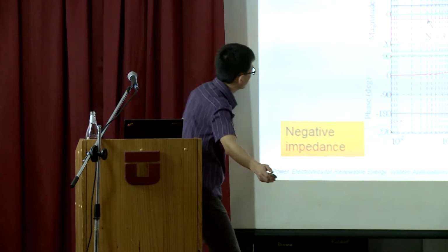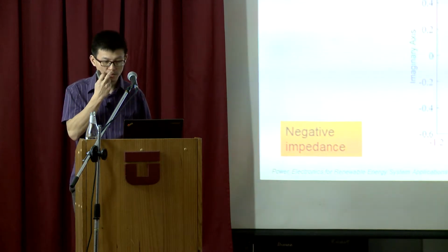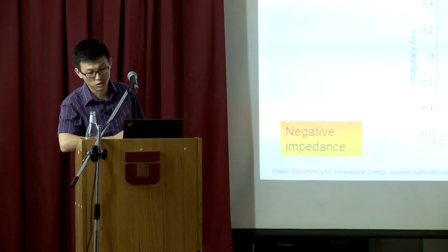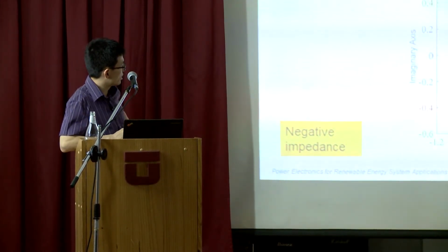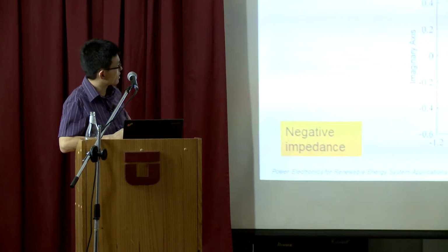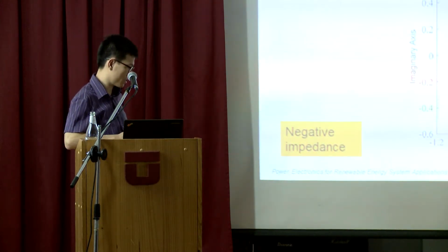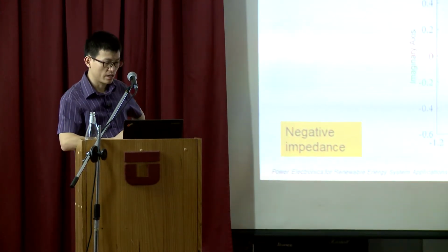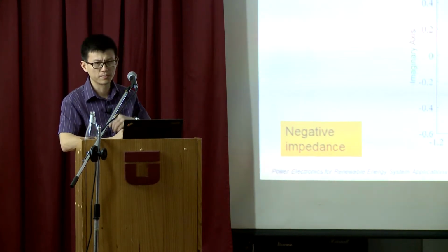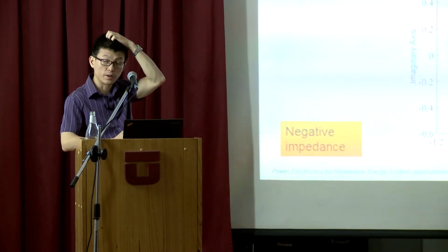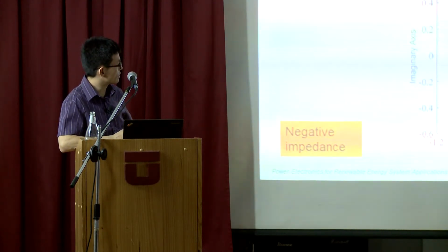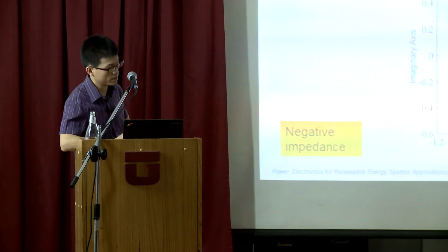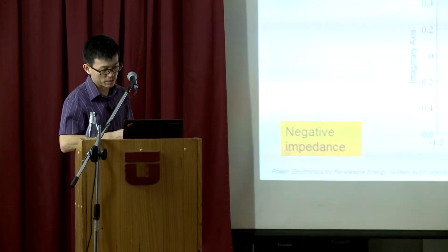If you want to see more clearly, this is the Nyquist diagram. Essentially, assume the local droop gain Ki is fixed. What we find is that when there is this pole here, the Nyquist diagram starts to shrink towards that direction. In that case, it increases the safety margin, or the stability margin, of the system. So it is very clear that when the number of multiple sources increases, the system actually gets more and more stable in general.